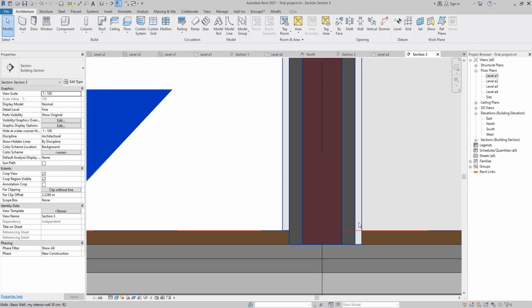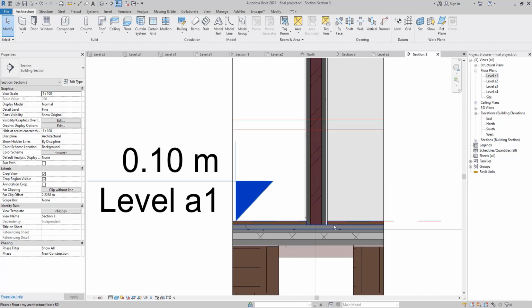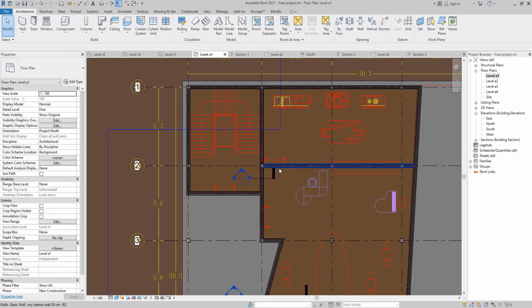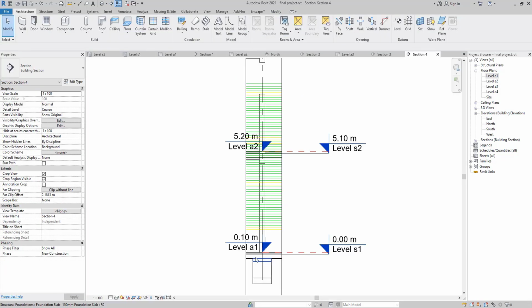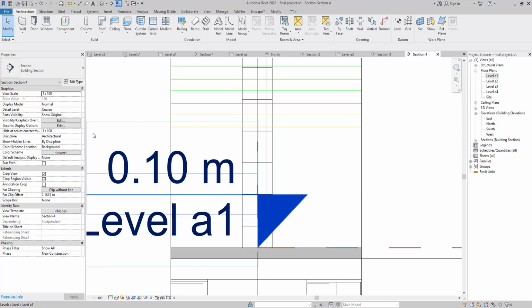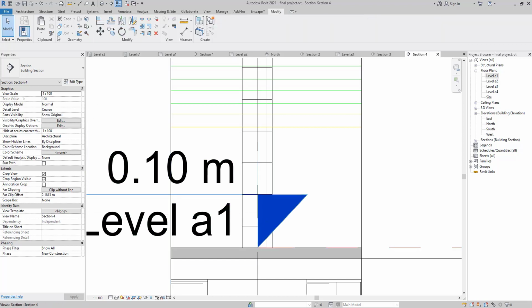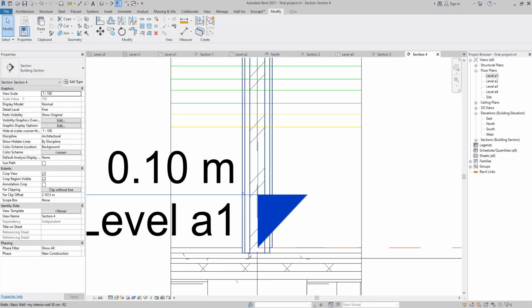So this is the reason we are also going to use the cut element, or you can just leave it like that. The next step is to use this cut tool for most of your interior walls, and it's much easier to do this process whenever you are drafting your wall. For example, go here, use the join modifier and join your wall. You can turn on the fine view and we will see it's all right.